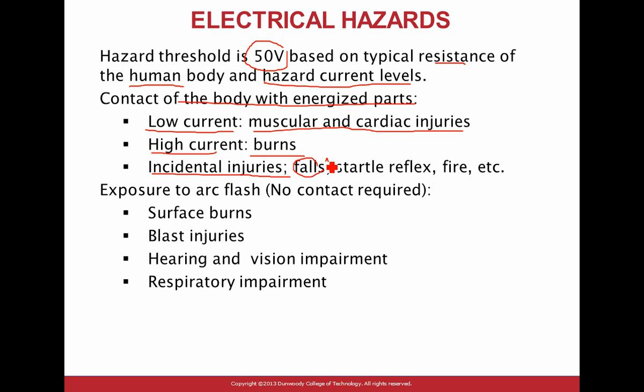At that time, there were electricians working the panel. When the transient came, they were using voltmeters that were not rated to verify the absence of voltage. Long story short, because of the higher voltage transient, it shorted right through the meter. He panicked and dropped the meter into the panel. Now you aggravate the situation: big ball of fire. I think 3 people died from that incident, but it was a big piece of equipment.